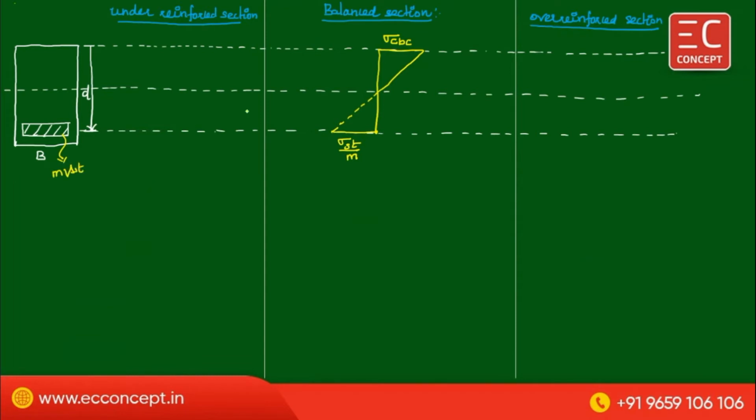Now this is the compressive zone, this is the tensile zone, and the force acting on the tensile zone is T, and the force acting on the compressive zone is C. The distance between these two forces, the lever arm, is equal to D minus XC divided by 3.